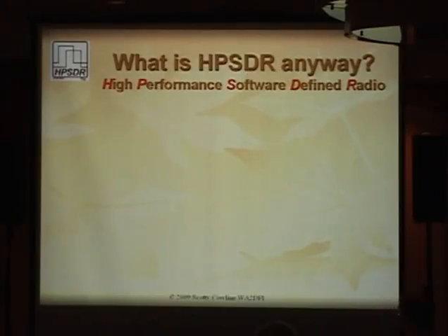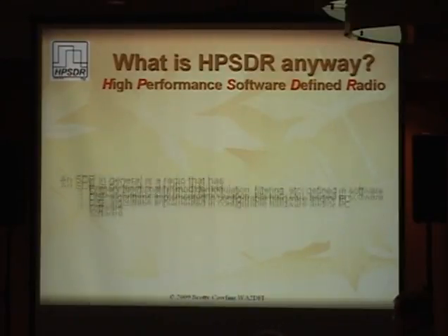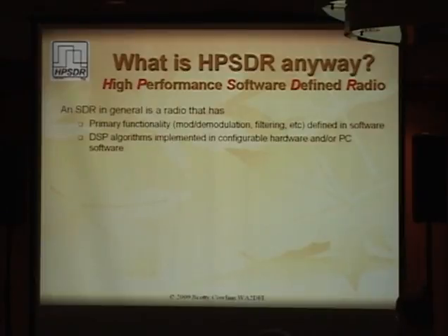For the people who didn't raise your hands, I'll give you a little bit of basic background of what HPSDR is. But I won't dwell on it too long because I really want to focus on the new stuff that's coming. So for those who don't know what it is, it's high-performance software-defined radio. And SDR in general, as you probably all know, means the functionality of the radio is defined in software as opposed to a software-controlled radio, which most of us are used to, at least in the past. We usually use DSP algorithms in the software or firmware in the SDR hardware itself, like in FPGAs.